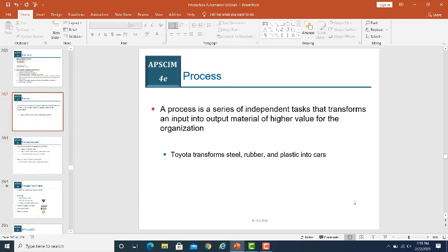So, in most of the cases, you will also need to analyze the processes because the cycle time of the system and production rate of the system depends on the processes. The bottleneck station that you identify, that is basically the processing time of any activity. In process analysis, we normally study and analyze the activities that happen within the system.